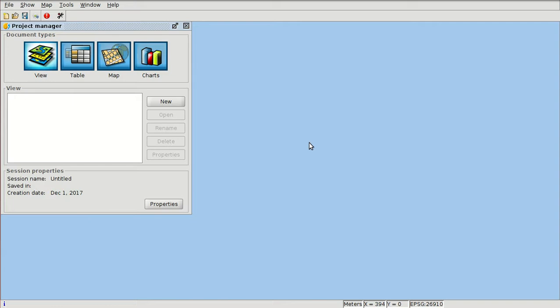In this new module, we are going to see the editing tools in gvSIG. We can create new vector layers, we can create point, line or polygon shapefiles, and we also can edit the existing ones. For example, we can edit a DXF file, and we also can edit a DWG file, but we will have to record it to save it as a DXF file.